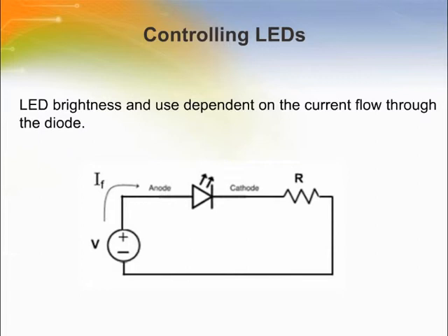Because different colored LEDs are made of different materials, they all have different trip points too when the LED turns on. A typical red LED may require 1.7 volts at 20 milliamps, while a blue LED will require 3.6 volts at 20 milliamps. The brightness of each LED will waver if the current flowing into the LED wavers. For this reason, the drive circuitry for LEDs must be controllable and stable.